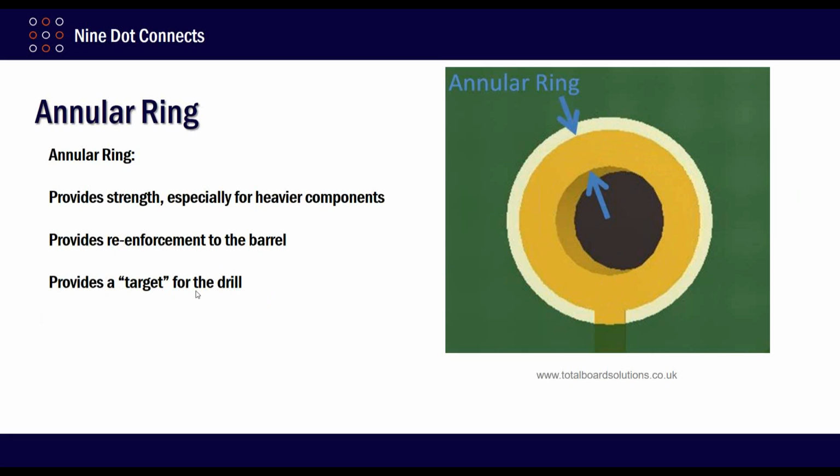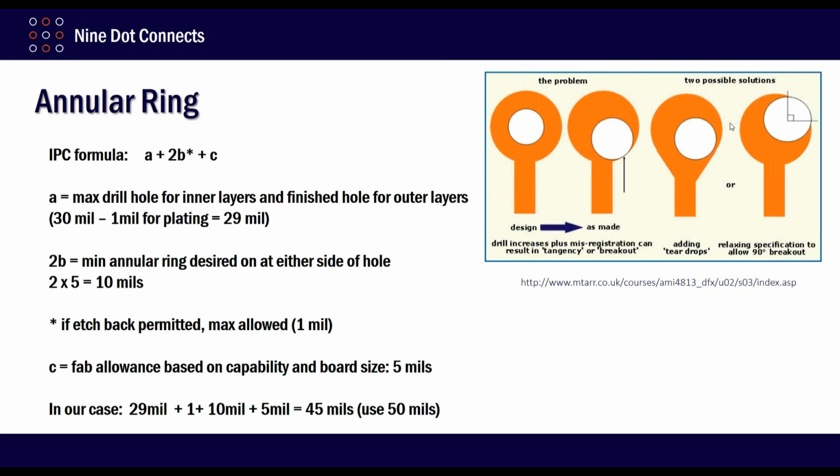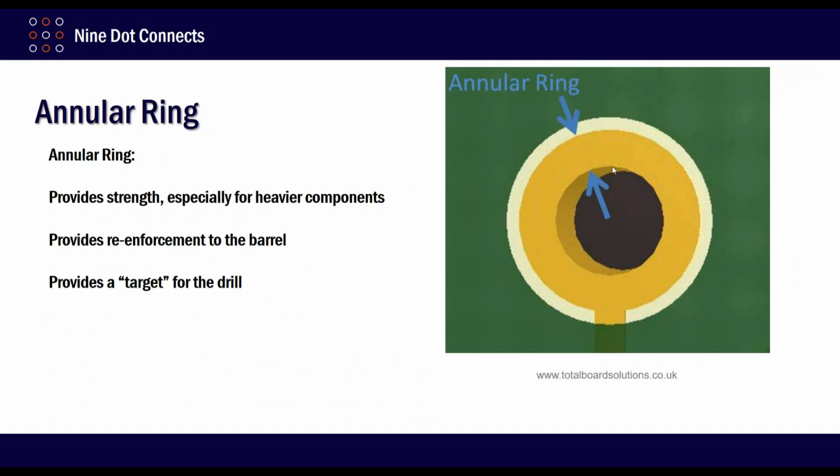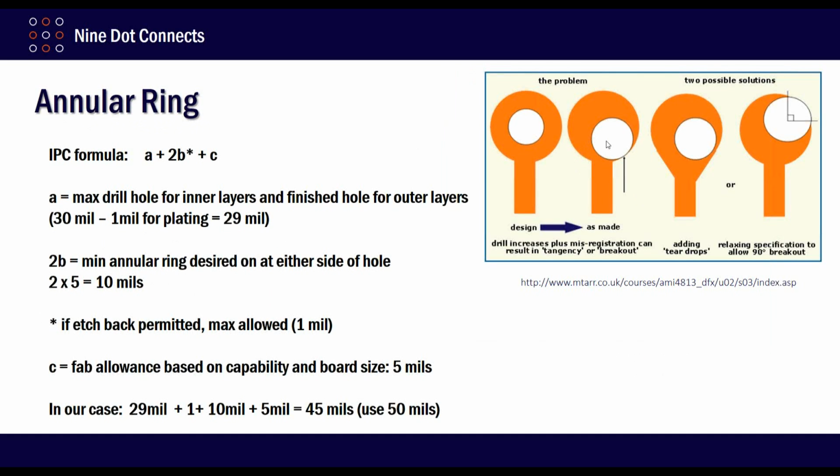Now, what do I mean by that? Well, one of the biggest problems you have, and again, this deals with the classes, is that in an ideal world, it would be like this, okay? But in the real world, there is going to be some travel by the drill. The drill is going to go in at an angle, okay? And it's not always a perfect thing. And of course, there's what's called registration as well. And I'll talk about registration here on part C.